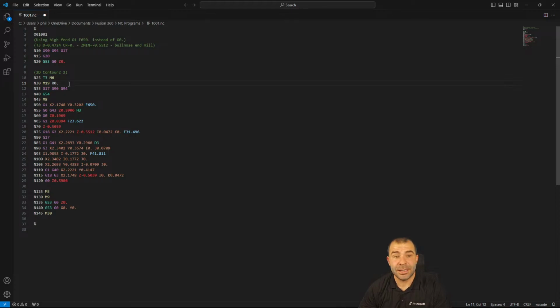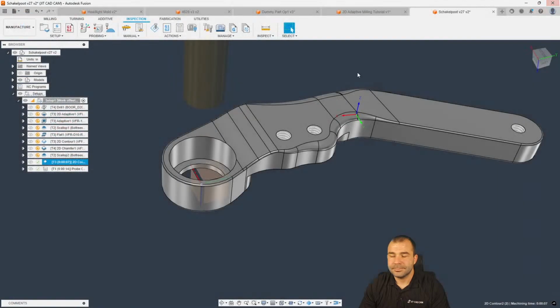Depending on your machine, you can sometimes say, I want to rotate R15 to clock that to 15 degrees from R0, right? So if your R0 is your tool change zero, then you want to go 15 degrees from that. That would be the key thing to look out for on most machines: you need that broaching tool to be in the 12 o'clock, 3, 6, or 9 position, right? So we can use that R to compensate. Hopefully that answers your question. Let me know in chat.